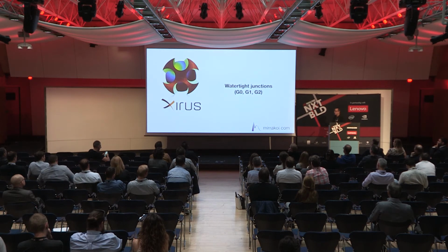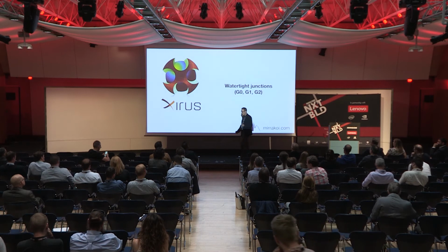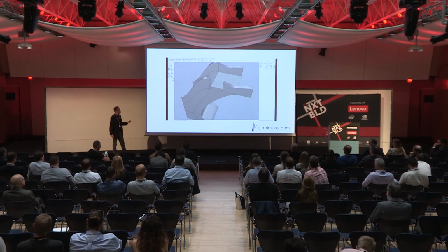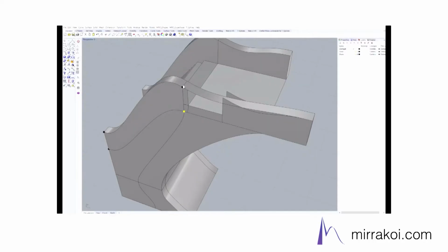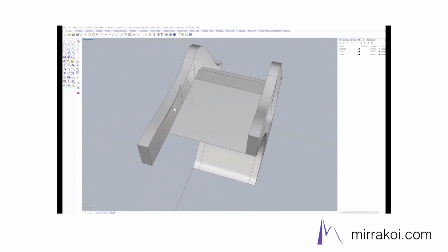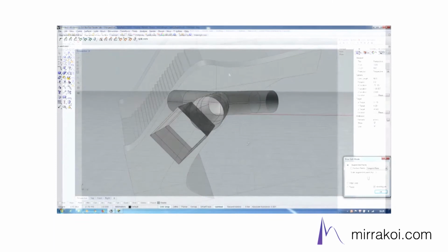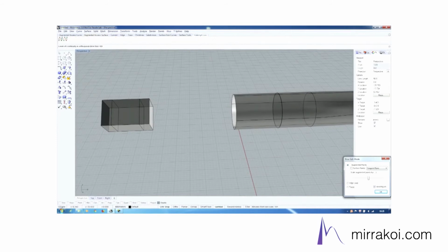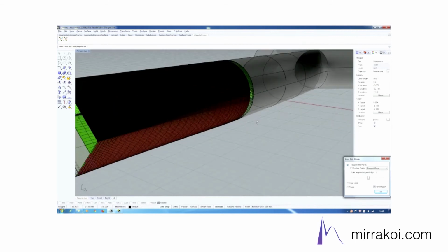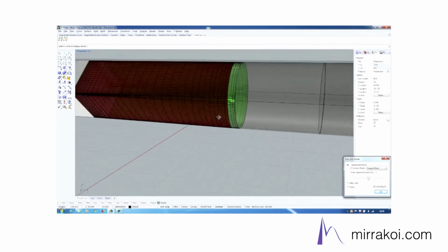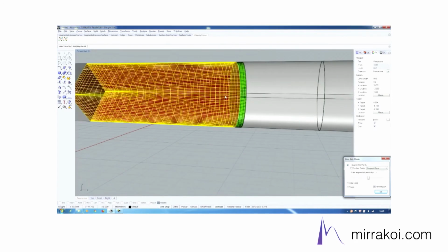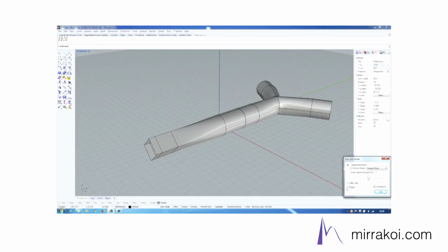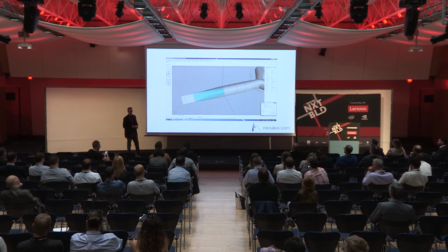Another thing that people in the AEC industry who work with us really jumped on. We didn't know this was such a big deal or such a huge requirement, but it's to create watertight junctions between surface patches. What we have come up with is a very simple way of just choosing patches, choosing edges on patches or subsegments, and just connecting them, independently of topology. For example, here you can connect a box or a square shape to a cylinder that has a circular shape, and you can choose what kind of continuity you want. You have different options: G0, G1, or G2, and then with a bunch of mouse clicks you get some previews, choose the one you want, and you have it. If you apply an offsetting operation, you can manufacture this surface. This is really quick and very simple, and gives you some new opportunities